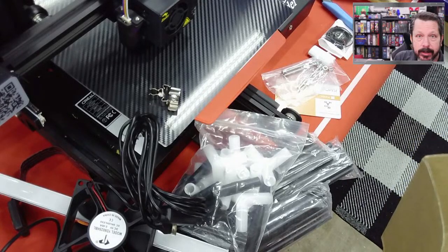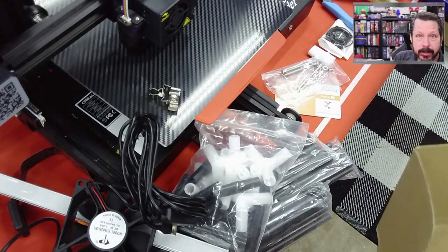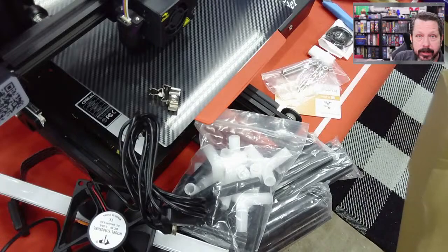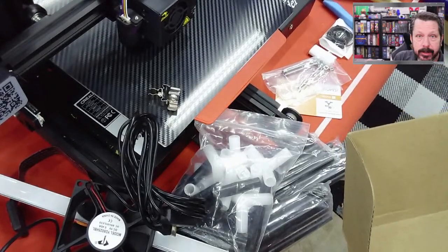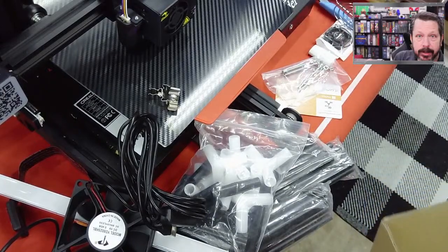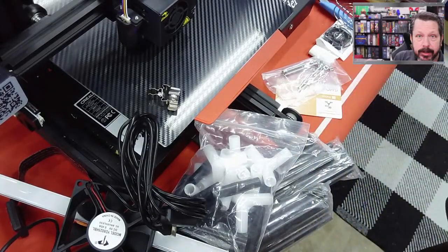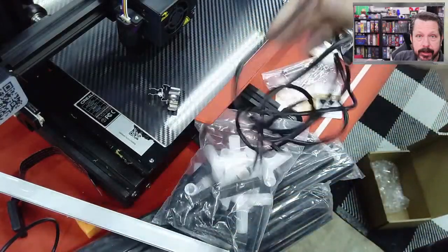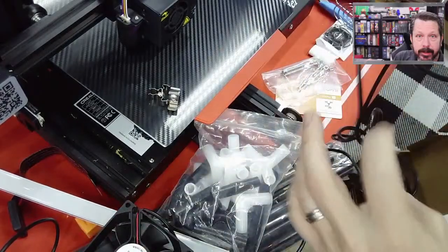It's kind of like a budget, you know, where you've got 2.5 amps and every little thing eats up some of it. I am not powering the printer with the Raspberry Pi itself, so I don't have to worry about trying to supply power to the heaters or anything like that. But I am now powering a LED bar, the screen that's on the Pi, I'm powering that. The Pi itself is getting powered. I said the LED, and now this fan. So let's plug the fan in and see if I can power both of those at the same time without some kind of brownout situation.